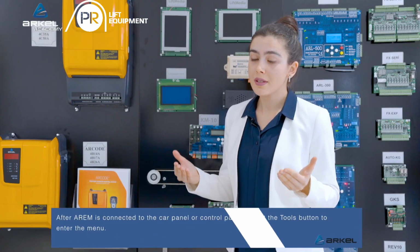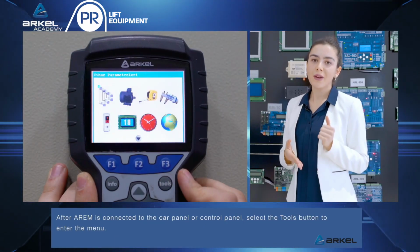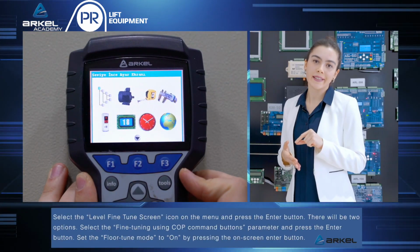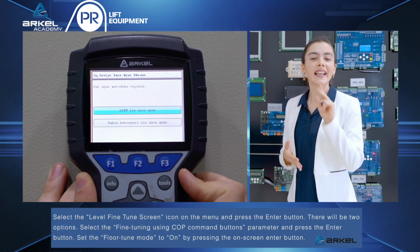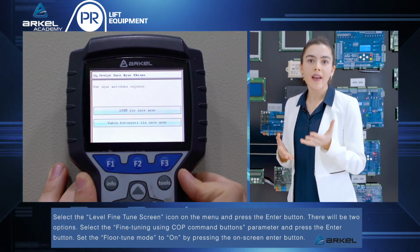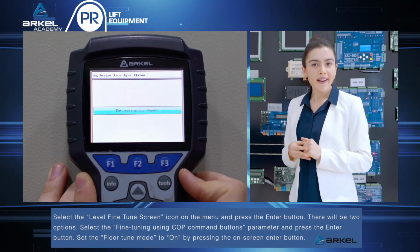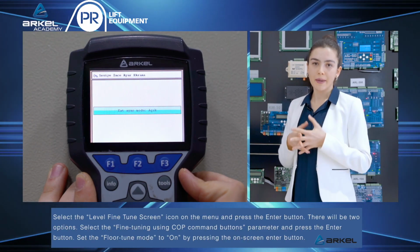After RM is connected to the car panel or control panel, select the Tools button to enter the menu. Select the Level Fine-Tune screen icon on the menu and press the Enter button. There will be two options. Select the Fine-Tuning using COP command buttons parameter and press the Enter button. Set the Floor Tune mode to On by pressing the on-screen Enter button.